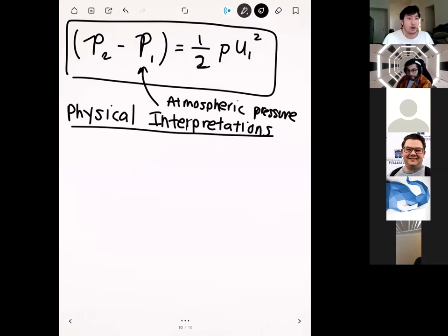And so far, when we derived the Bernoulli equation, oh, so question. Just to double check, more pressure equals faster flow? It's not that more pressure equals faster flow. A bigger pressure difference means faster flow. Right? Pressure by itself doesn't produce flow. We saw that with our hydrostatic cases, right? Just because you have pressure, you don't have flow. But if you have differences in pressure, that doesn't have anything to do with hydrostatics, then that can produce flow. So if you have two horizontal places and the pressure difference between them is really high, that's going to drive the flow.